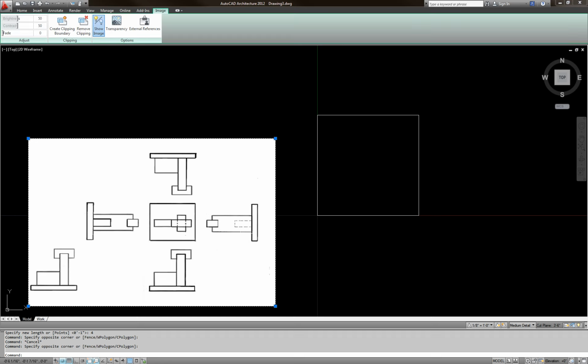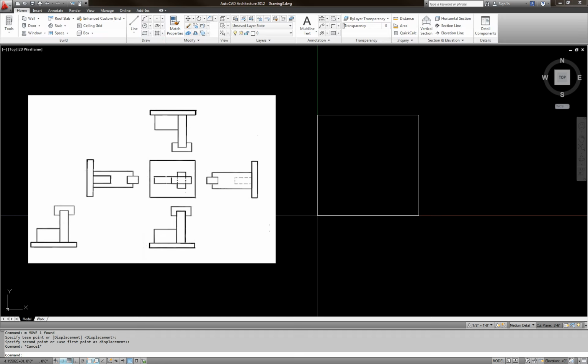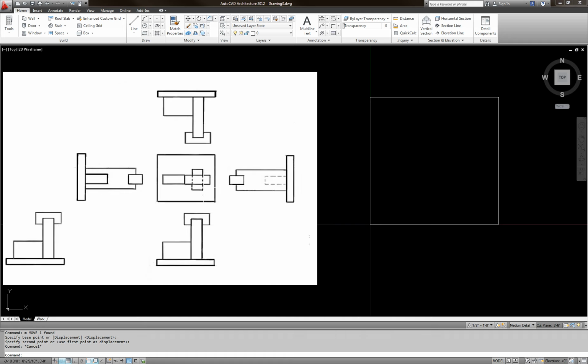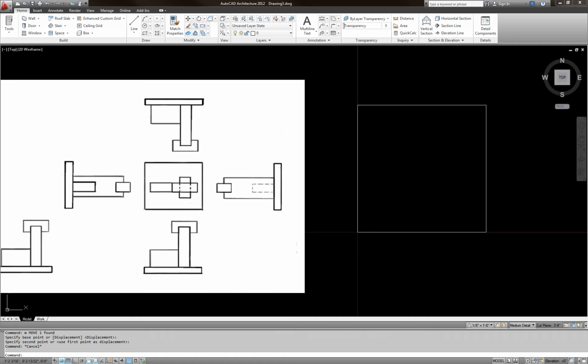So what I'm going to do now, I'm simply going to draw this guy here, the bottom piece. So I have this 4" by 4" base here. Okay, so REC enter. I'm going to click anywhere inside the 8" by 8" rectangle. I'm going to add 4 comma 4. That's my 4" by 4". REC enter. Click anywhere on the screen at 3 comma 3.